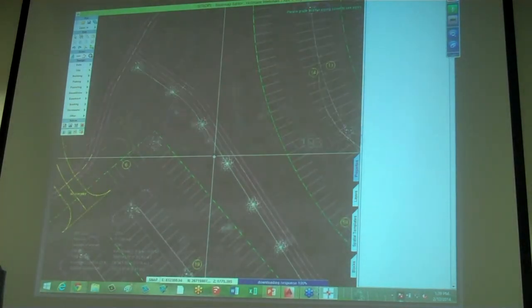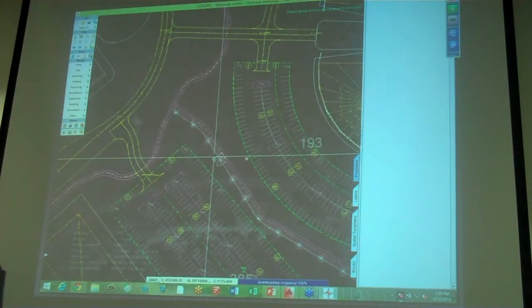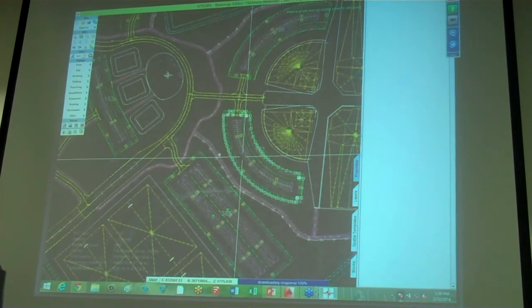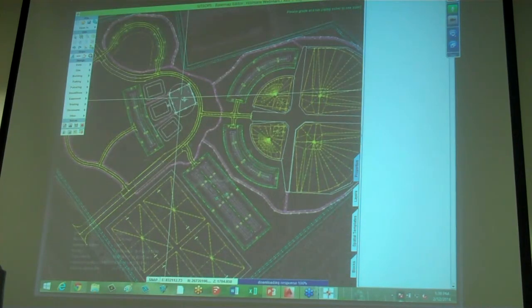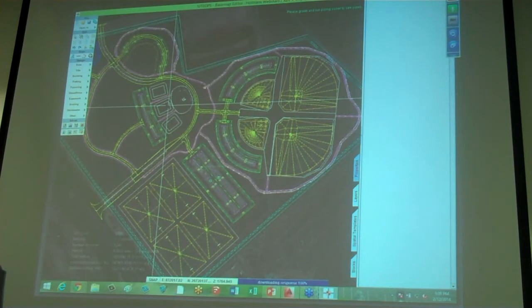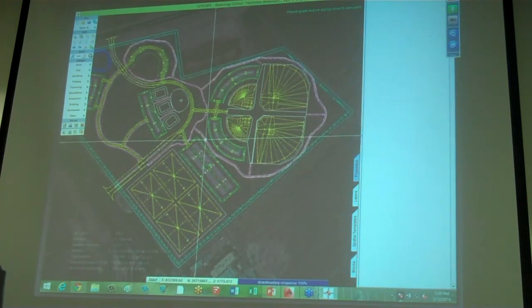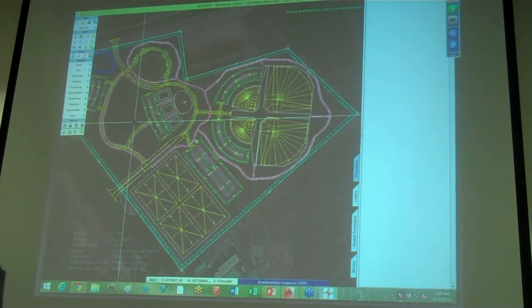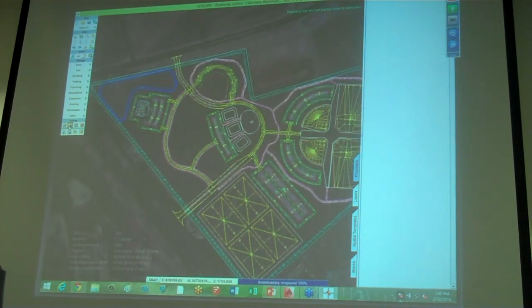They do different scenarios. You can see I got some curb parking, and there's my little splash pad area in the middle, some basketball courts, and the sidewalks. You can actually link those tree lines to the sidewalk. So if you change the sidewalk, they'll change for you. And every 500 feet, I want a park bench. The park bench costs so much. So if I hit the grading plan here, we're going to say let it grade.